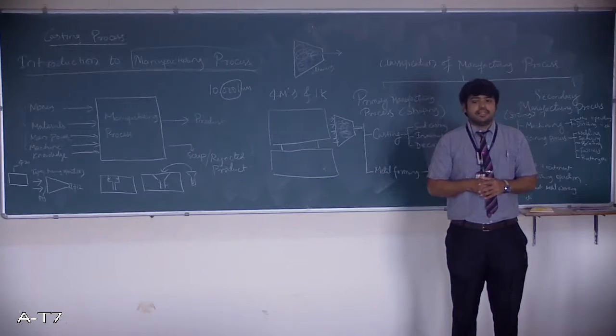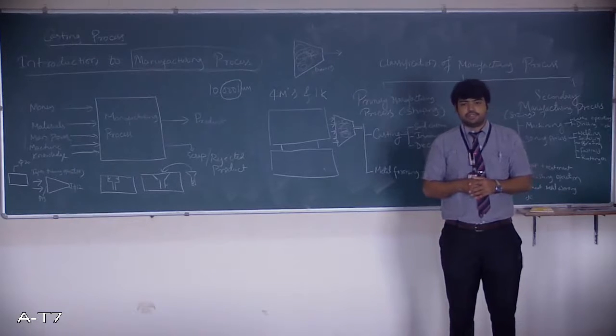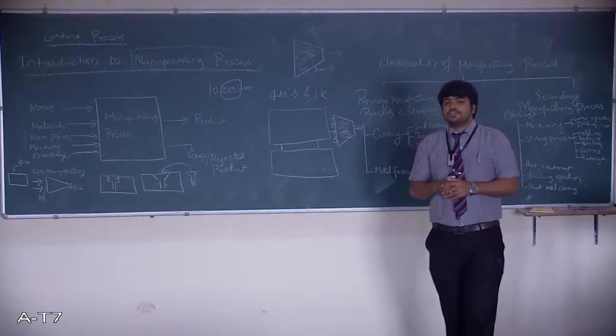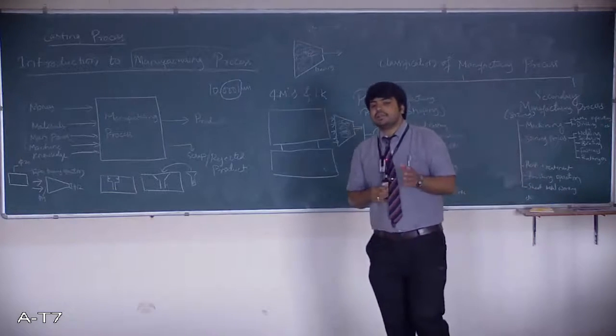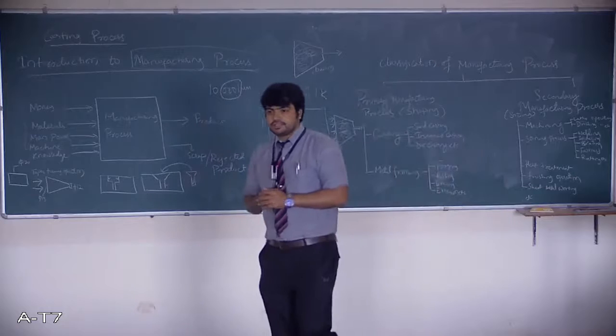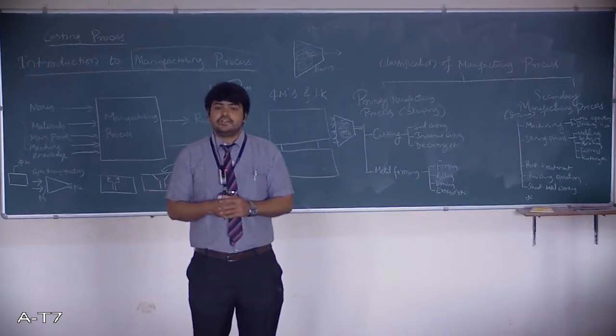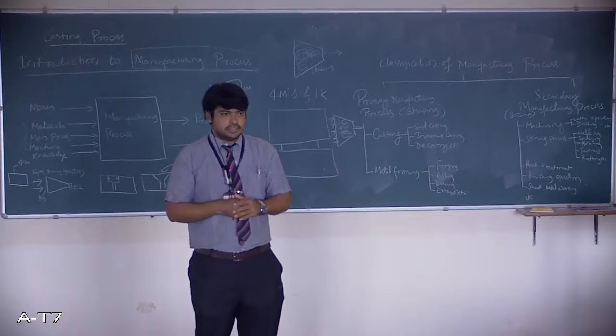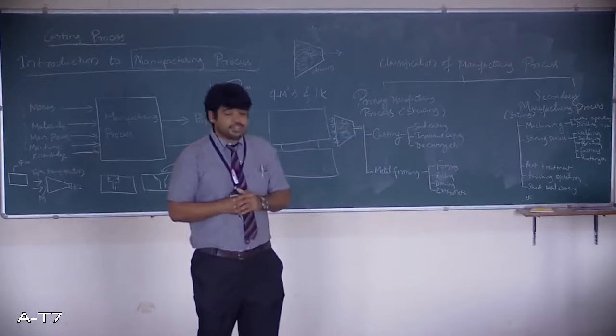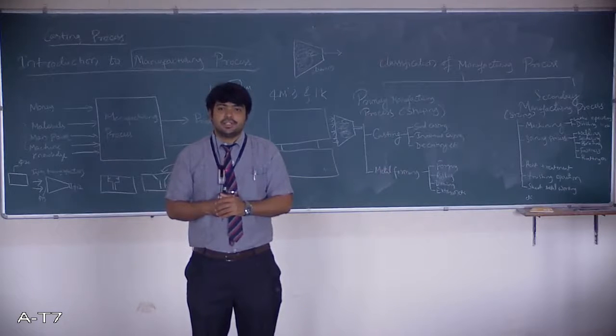In most welding processes, we are going to have the filler metal. Wherever we make use of it, the filler metal will have the same composition as the workpiece, and the temperature in welding will be nearly equal to the melting point of those workpieces. Brazing is a weaker joint as compared to welding. We will come to this particular difference between welding, soldering and brazing in unit number 4.